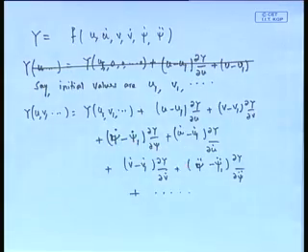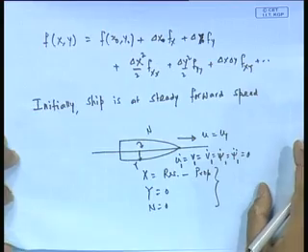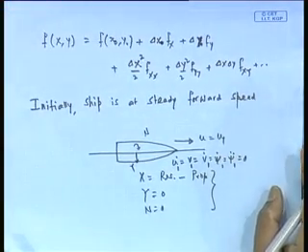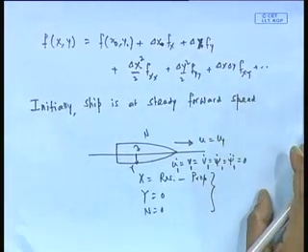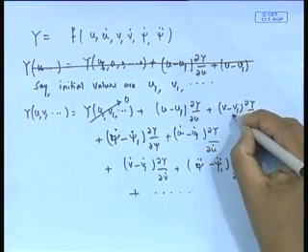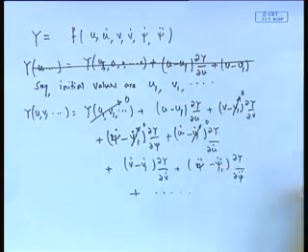That is one. What is my Y value at initial? Also 0, because remember this value is the value in this direction in the initial state, that means when it is going on a straight line. What is the Y force? Obviously 0, because there was no Y force. So, for this particular condition, that is, if I expand Y about an initial condition which is the straight line steady motion of the ship, then I have all this 0, etc. So, what do I get?